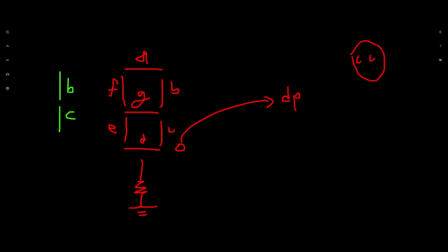In the same way, let's say I want to show number 2 on the 7 segment display. It's pretty simple now. I'll just activate A, B, G, E, and D. That's it. In the same way, if I want to print 3, I'll just activate those LEDs.